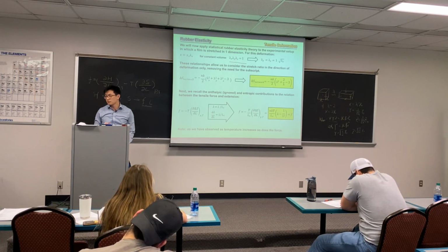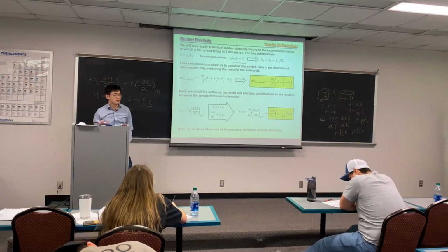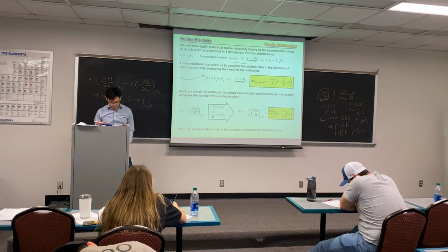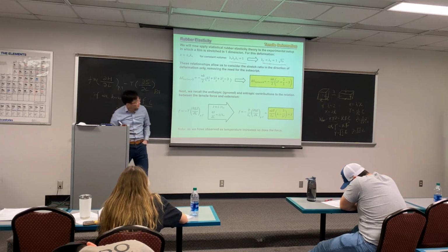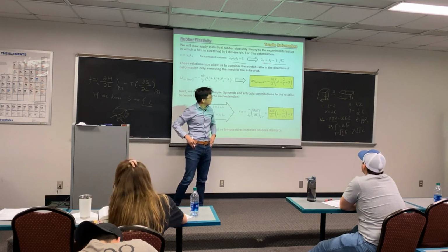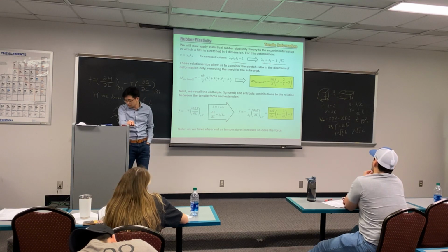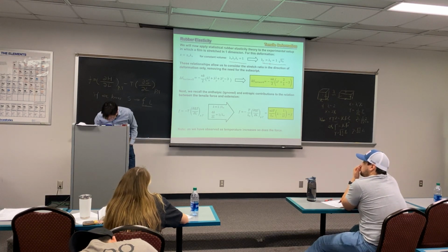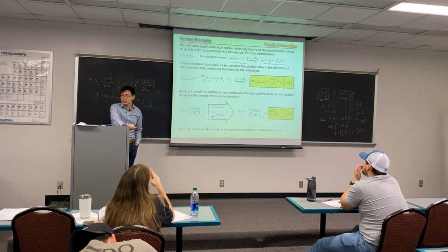Your deformation in one direction multiplied by the other directions will be 1, so there's no change in the volume. And we can use this to get lambda y and lambda z, as we also discussed. Lambda y and lambda z will be equal to, this is missing a slash, 1 divided by the square root of lambda x.